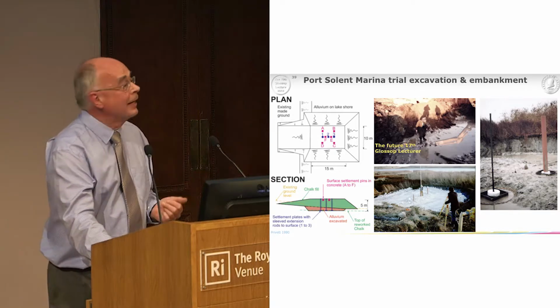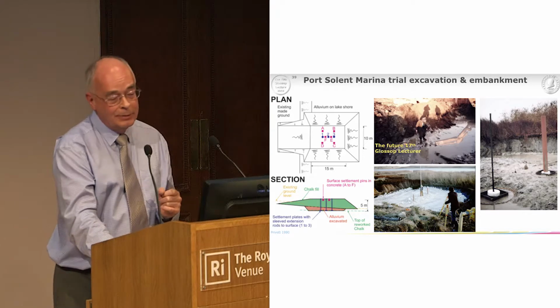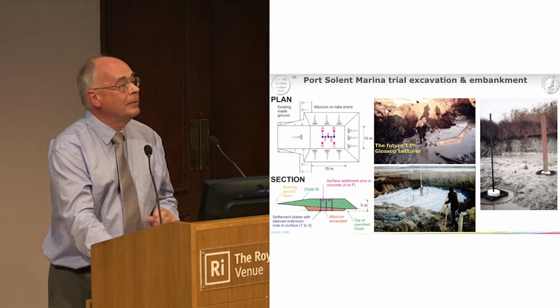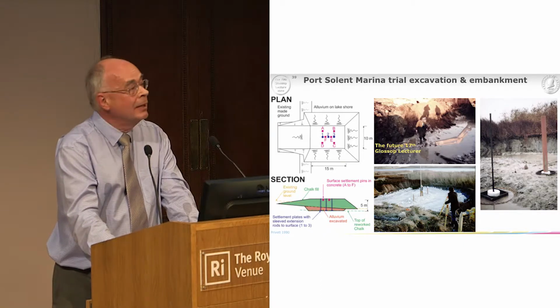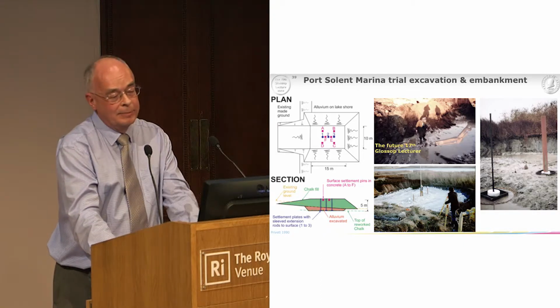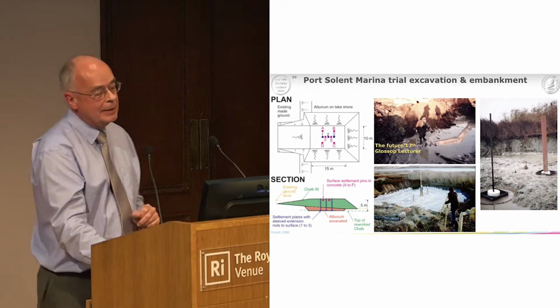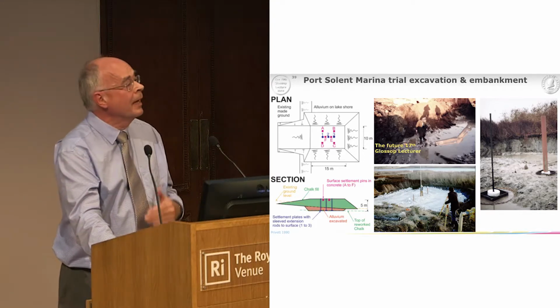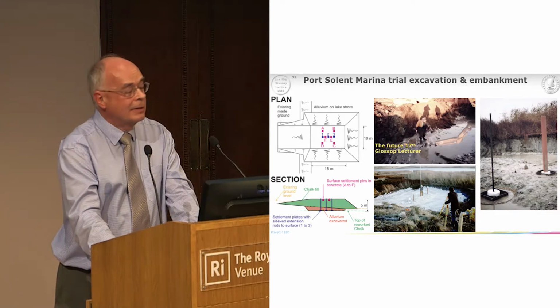And it wasn't going to be as bad as we thought, and the water wasn't coming in quite so much as we thought either. So we placed 3 1-metre diameter settlement plates on the formation with rods attached to these plates that came up to the top of the fill, sleeved by a plastic sleeve, so we could measure settlement. And as we were filling, we started levelling these rods, and therefore were measuring the settlement underneath.